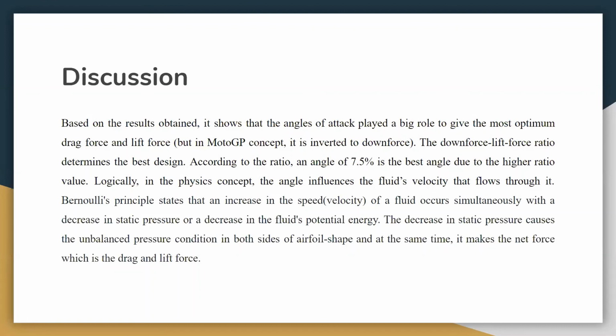Logically, in the physics concept, the angle influences the velocity of the fluid that flows through it. Bernoulli's principle states that an increase in the speed of the fluid occurs simultaneously with a decrease in static pressure or a decrease in the fluid's potential energy. The decrease in static pressure causes an unbalanced pressure condition on both sides of an airfoil shape, and at the same time it creates the net force, which is the drag and lift force.